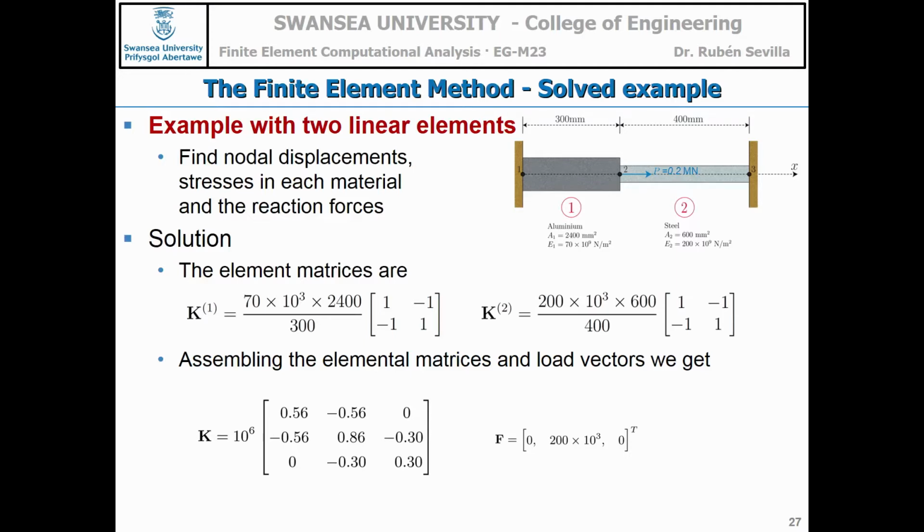And how many actual unknowns do you have in this problem? I have 3 nodes in theory, but how many real unknowns do you have? 1, 2, already heard a few answers. 3, 1, 2, or 3. Well, you would say another number, isn't it? Do I know the displacement on the left? Yes. Do I know the displacement on the right? Yes. So 2 of these guys are not unknowns. I have 3, but 2 of them are actually known. Only 1. Okay?